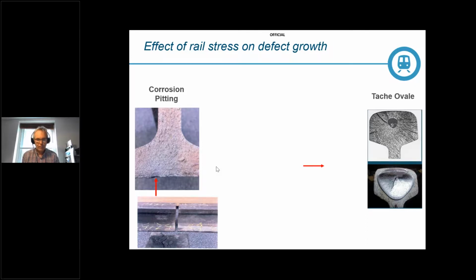The corroded rail will develop slowly over time, but as the rail is already old, corrosion pitting on the underside of the rail foot is likely to have developed, and poor pad condition will exacerbate this. Corrosion pits on the underside of the rail are not ultrasonically testable unless they lie underneath the web, because remember, we look down through the rail head when we're testing things. So corrosion pits that are well out from the rail head are very difficult to find.